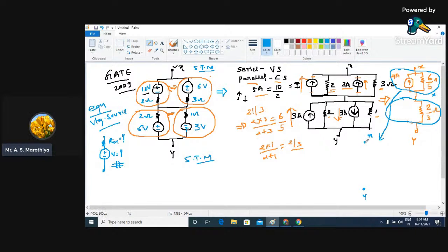So it is going to be a resistor followed by a voltage source. Now what will be the value of this resistor? It is going to be equal to the internal resistance. Here the internal resistance is 6 by 5, so the same 6 by 5 is going to appear over here. Now we need to find the magnitude of this voltage source, which is V. V is nothing but I into R. So I is 7, R is 6 by 5. 6 sevens are 42. So this is going to be 42 by 5 volt.